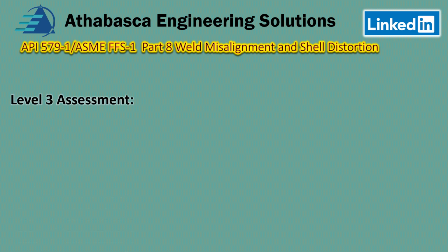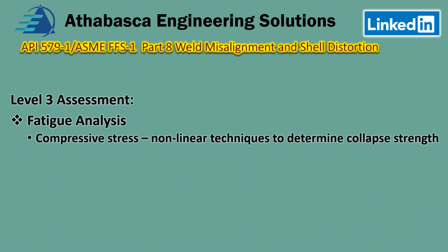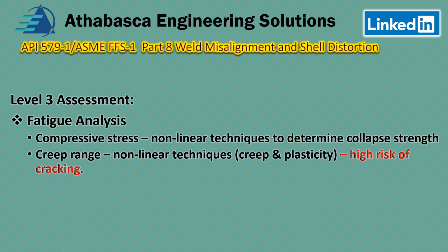Their comments with regard to fatigue and Level 3 assessment are that if you've got compressive stresses, they encourage you to use nonlinear techniques to determine the collapse strength. They also say that in the creep range, with nonlinear techniques, you need to understand the creep and plasticity of the material.